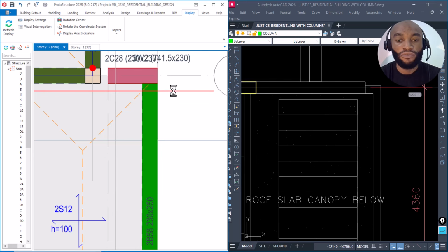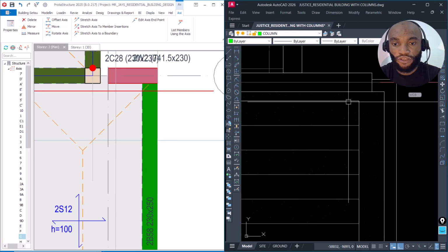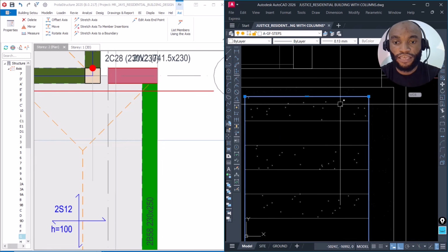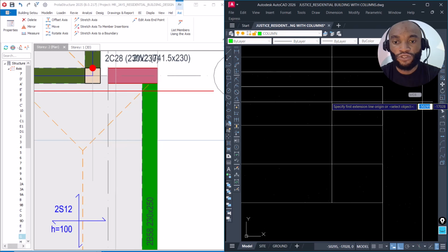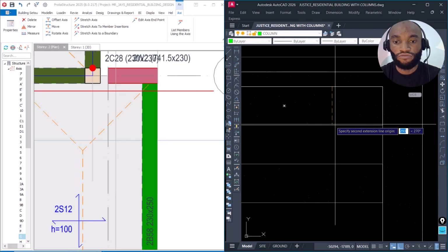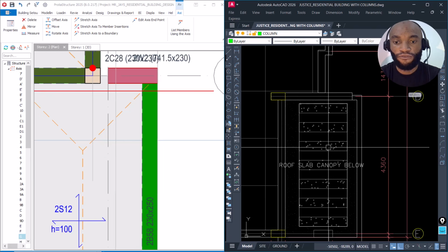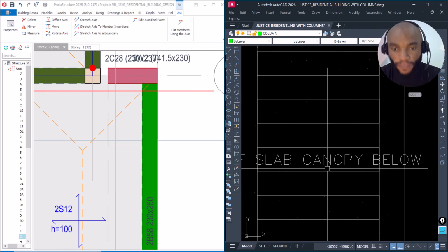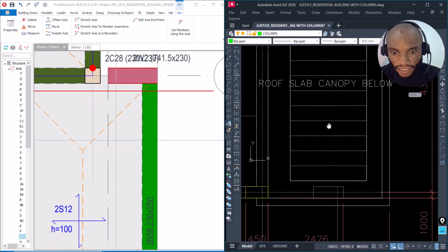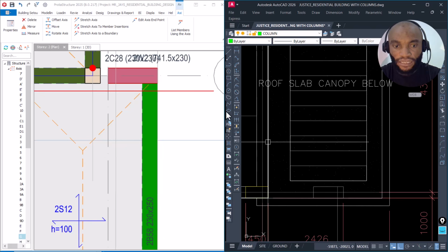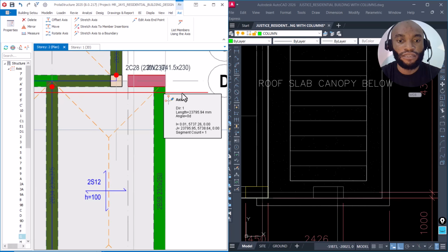On this, we have just established this first line here. So from here we'll have 300 distance. If you measure from here to here, it is 300. Okay, that is fine. And then we have 1, 2, 3, 4, 5, 6, 7, 8, 9, 10, 11, 12, 13. That's fine. So I'll now offset 300. Click on my ghost axis, right click here, and then say offset.